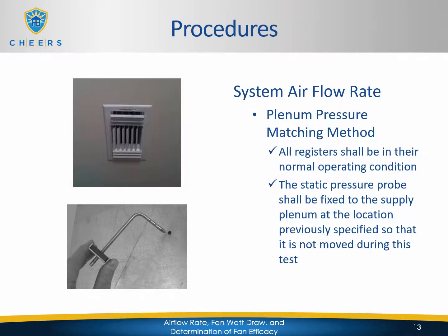All registers shall be in their normal operating conditions. And then the static pressure probe shall be fixed to the supply plenum at the location previously specified so that it is not moved during the test. So the pressure probe will go into the hole that was drilled in the supply plenum.